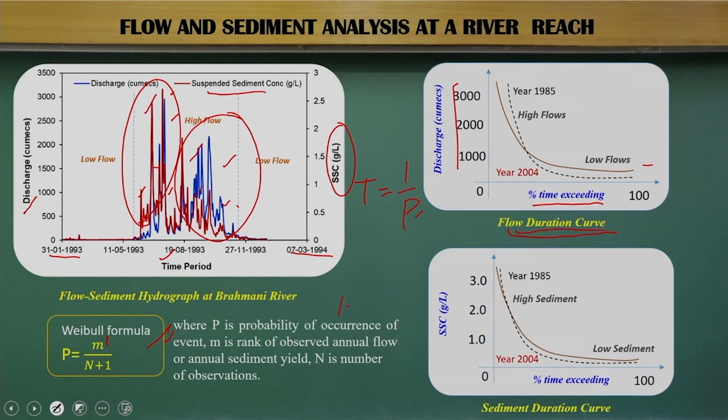Similar way, we can develop the sediment duration curve. The sediment data can be sorted, ranked, compute the probability, compute the time periods, and you can have a percentage of time of exceedance, which varies from 0 to 100%, and you have the suspended sediment concentration.